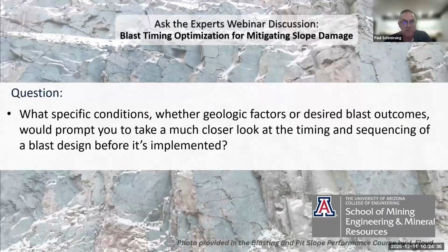The other thing that'll happen too in these corners is usually the outside row, which is the row closest to the wall. A lot of times there's extra holes in there because you're going around a gradual corner. And you need to slow the inside timing down so that way your angle initiation isn't rotating and impacting your ground or your corner hard. So I got corners, shot, recoil, shot direction, and faults.